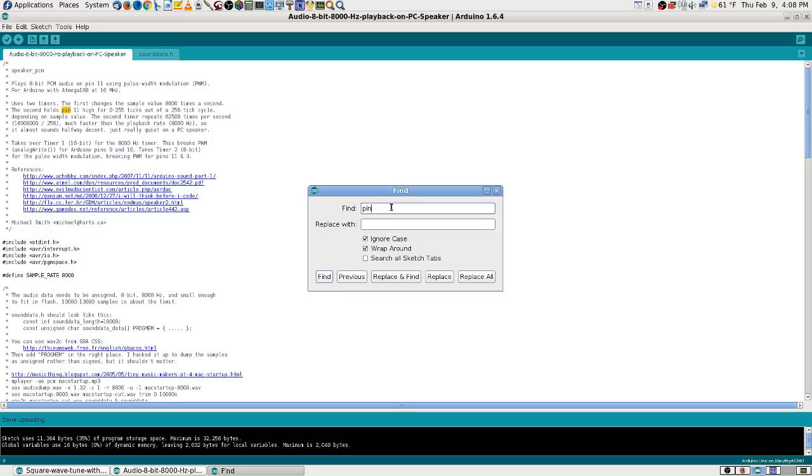And then, okay. Arduino pin, okay, breaks PWM. For Arduino pins 9 and 10, takes timer 2, 8-bit for pulse width modulation, breaking PWM pins 11 and 3. Whoa, hang on. This breaks PWM and for Arduino pins 9 and 10, takes timer 2, 8-bit for the pulse width modulation, breaking pins 3 and 11. So this kind of got me going around in circles now. Okay, so are they using all 4 of those pins? Do I have quad sound here or what?